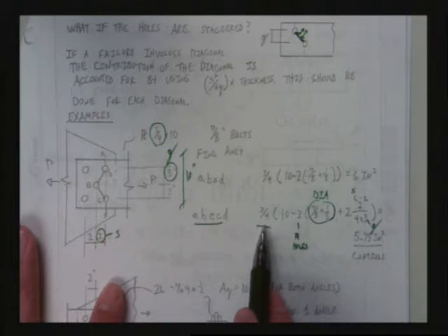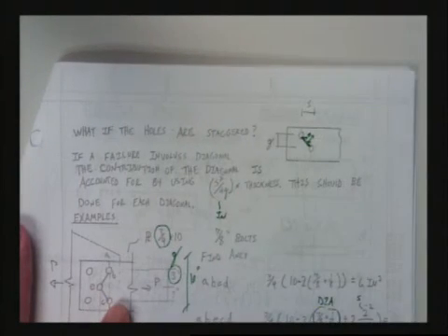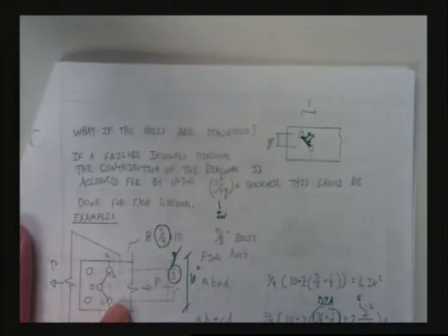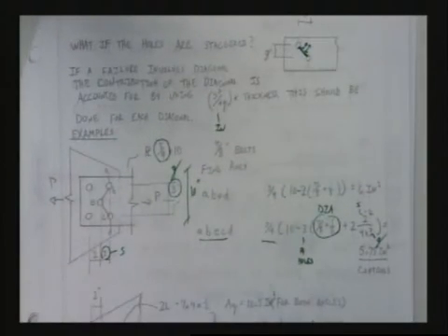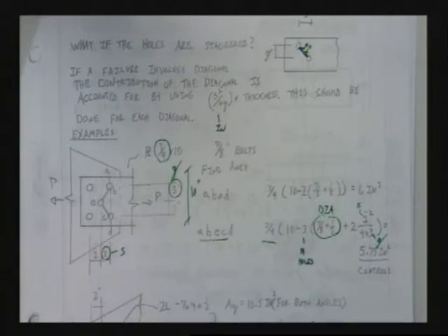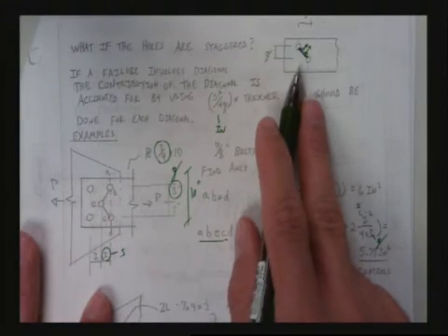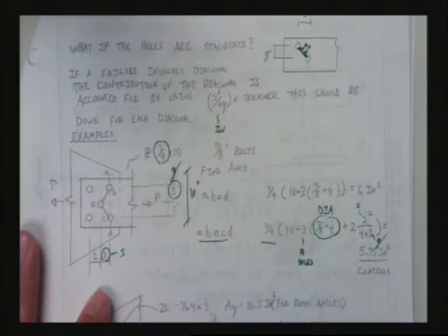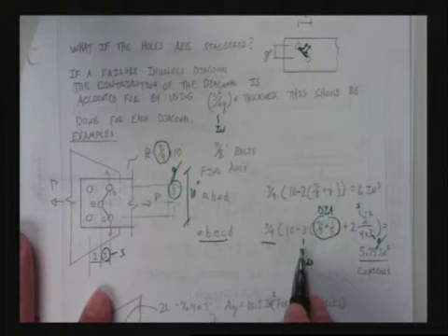And it's kind of cool that if you actually do the math on this, the units turn out to be inches. There's not an area we're getting here. We're getting a length calculation, this additional length. And it's a prime question for me to ask you, why do we have this additional length? You could say, because we have tension and shear simultaneously. And we have more length as well, because it's across a diagonal, not just across a straight width. You with me? Okay.